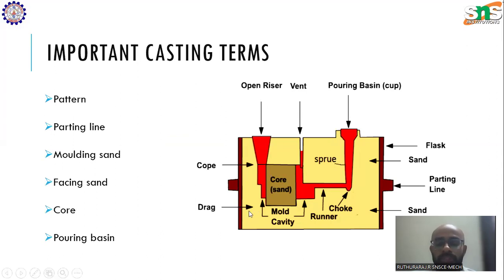How will we know if the metal is filled inside the mold cavity? Here comes the purpose of the riser. Once the metal is completely filled inside the mold cavity, it will rise through this riser. So we can predict that the entire mold cavity is filled.